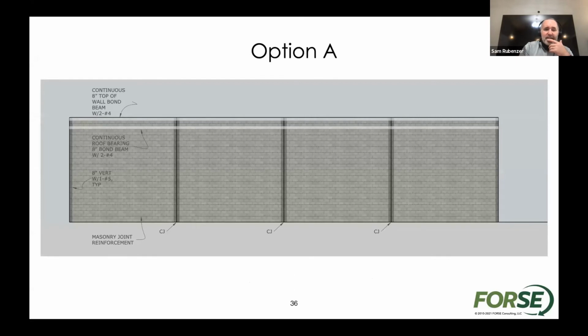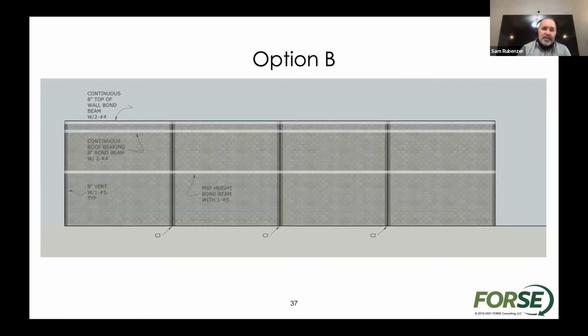Again, this is a pretty traditional looking Midwestern wall. We have these control joints pretty regularly, joint reinforcement. And so there's a lot of contractors that would prefer to just keep doing this. And there's a good reason why, this has been preferred here in the Midwest. We don't need a lot of other horizontal reinforcement. We have very low seismic, so this was probably preferred by most contractors for common walls that look like this.